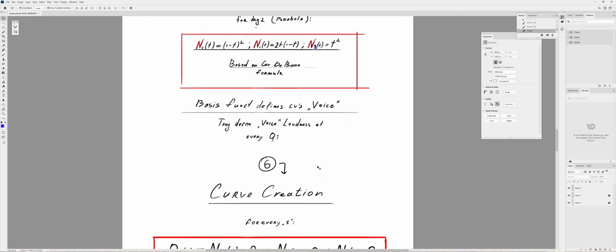Right. So what will happen next? We already have a lot of stuff. Once again, we have control vertices, which are our coordinates x, y, z. We have the amount of control vertices. We have the degree, the number of derivatives for our curve. We know that this is 2. We know the knot vector, and whether the knots are uniform or non-uniform. So does it have spans or not? In my example, it will have no spans, just one big chunk.